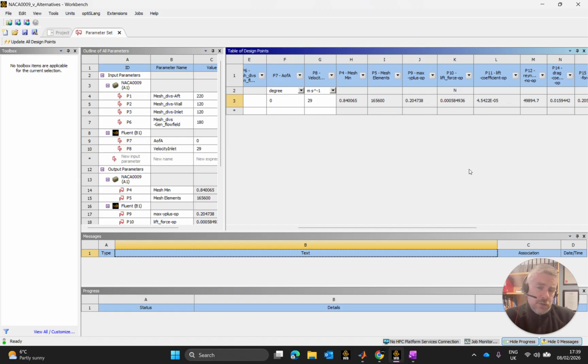The rolling resistance I'm going to try to minimize by looking after my wheels very well, and the axles and the bushes and so on, and just make sure that the wheels go round as handily as possible, as uninfluential as possible. And what I also want to do, obviously, is minimize my drag. Right, so this is what I'm going to look at. I'm going to look at the drag force here.